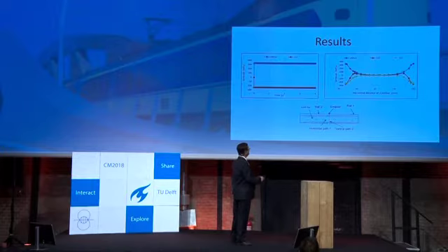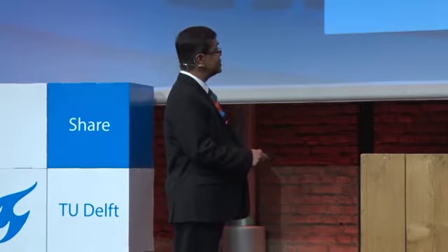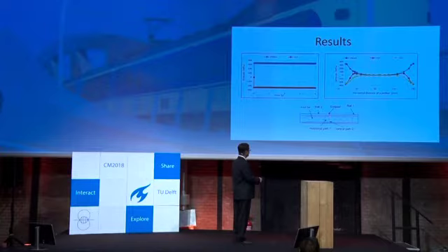You can see this is the S33 example. The value is somewhere here, which is 0. What does it mean? You can see the maximum longitudinal stress will be in compression here and in tension here. That means somewhere it will be 0. This is the position of the neutral axis.